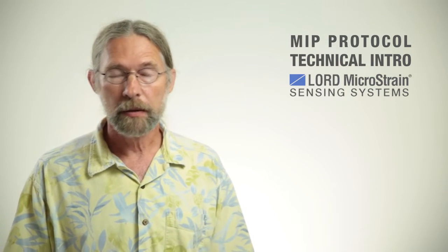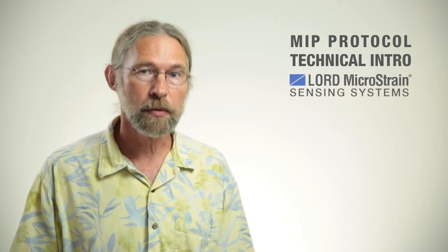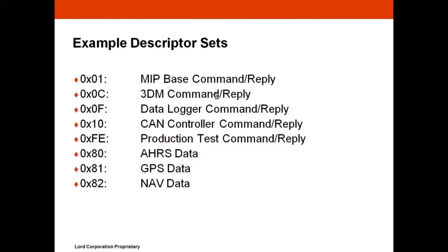All commands and data are fully described by the descriptor set plus the descriptor. The descriptor set is 1 byte, the descriptor is 1 byte. Together they make a 16-bit value that fully describes either a command or data. Here's an example of different descriptor sets, and you can see how they fall into different categories.